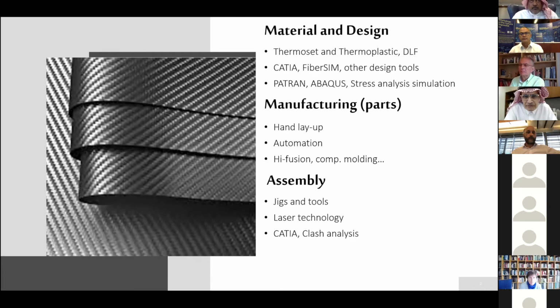So widely used in aerospace is thermoset material. We already have the mechanical properties and we know how to form it. The interesting part about composite is you really have to understand the manufacturing part of things before you start designing it. It's a little bit unlike the metallic world. In the metallic world, we used to design the part from a bulk and start making it, choosing aluminum 2024, 7075, or titanium or steel.